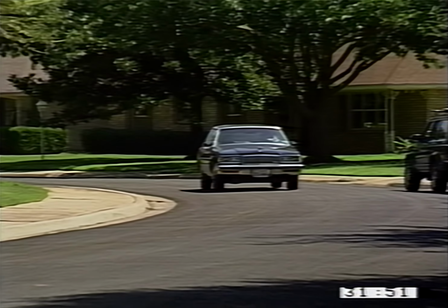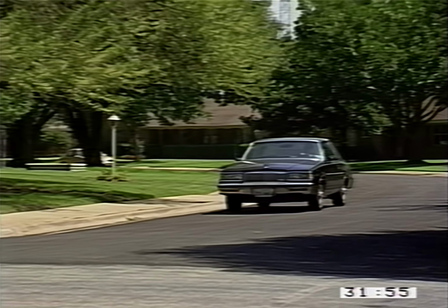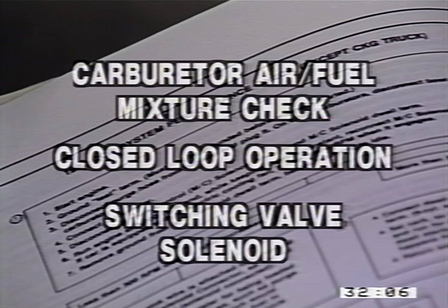Now, if there is a drivability problem but no code has been set, the system performance test is then used for diagnosis. The system performance check for full-function carbureted models verifies that the ECM system is operating to specs. It is a 3-step decision tree that includes a carburetor air-fuel mixture check, closed-loop operation, use of a dwell meter, and a switching valve solenoid check.